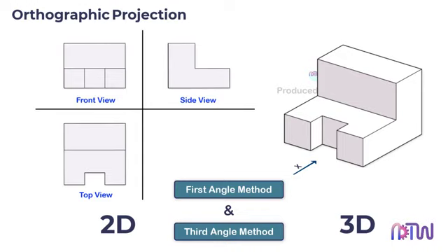In this video, we will learn how to draw an orthographic view from this isometric view of an object. Isometric view is a graphical method of representing a three-dimensional object. An orthographic view is a means of representing a three-dimensional view in 2 dimensions. It has only 2 axes. Let's see how we can represent this three-dimensional object in a 2-dimensional view.